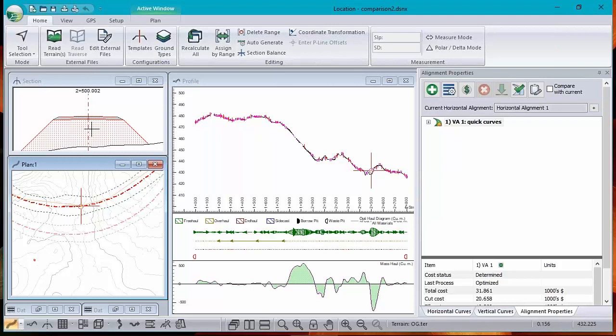You could think of this as a test for trying what? How about different template assignments, or different site preparation, or different overrides? So that would again modify your templates. So you can try what-if scenarios, and instead of, in the past, being forced to use two location design files, two DSN files or DSNX files, and have two location modules open at the same time, now you can just run location once and flip back and forth.